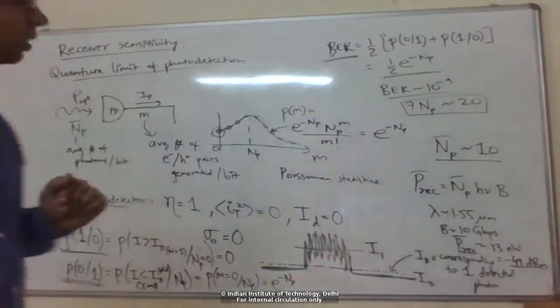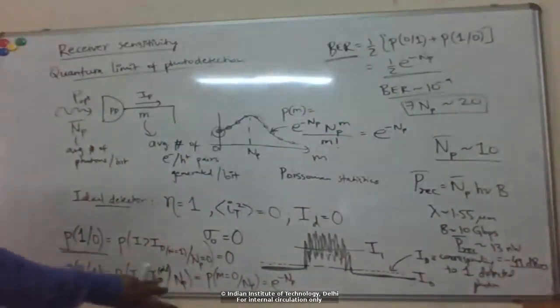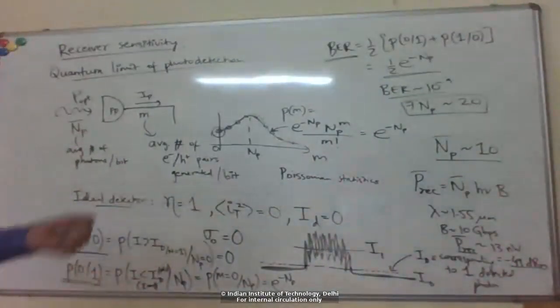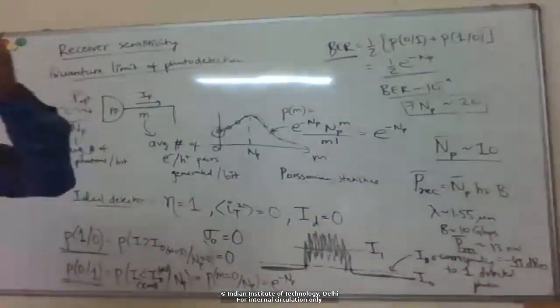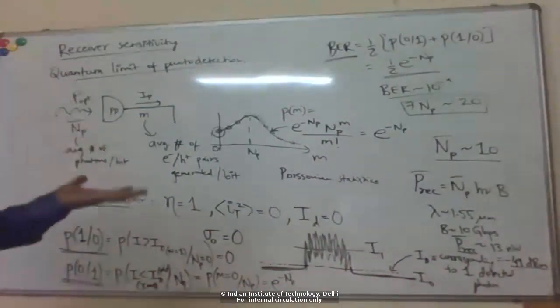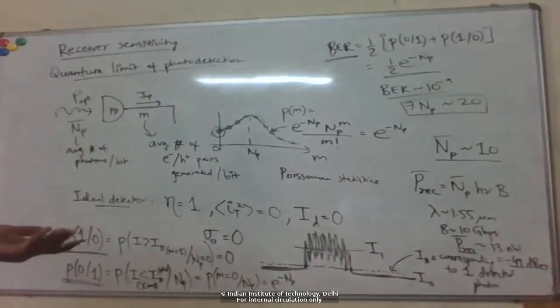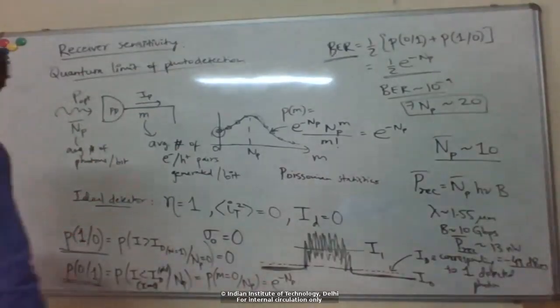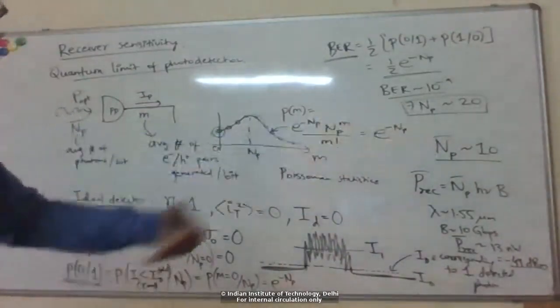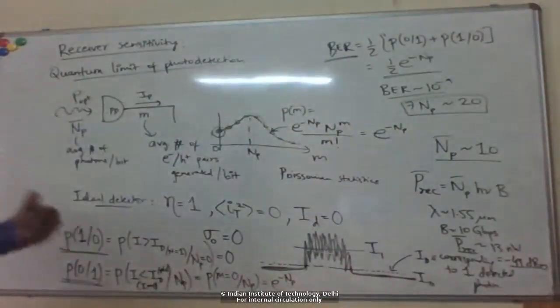Of course, you could have other noise sources in your link apart from the receiver itself. For example, one case we already discussed is directly from your laser transmitter: you could have relative intensity noise. Then we'll see that optical amplifiers along the link would also add their own noise.